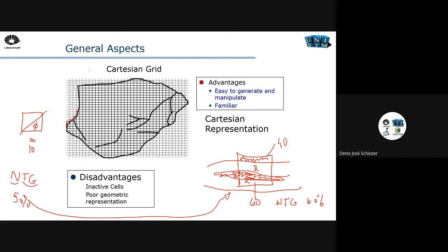So I can use a Cartesian grid for a complex reservoir, and I can use some special things that are inside the simulators already. You have to just select this option in order to cover these aspects, okay? And you can see here that you have a lot of blocks outside the reservoirs, and the only thing that the simulator will do automatically from Petroleum to simulator is, for example, say that these are null blocks. Null blocks, meaning that there are blocks, they are there, but they have zero porosity, so there will be no fluid there, no flow, okay?